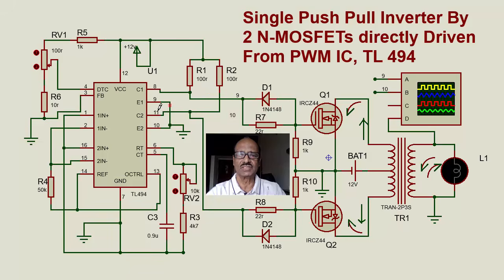So first it goes high and then it goes to ground. So this discharge takes place through this diode. Similarly it happens with this. And then the R and C, as you can see, is selected here. C is this one, R is this one, for selecting the frequency. Error amplifiers we are not using, that is why we have just given some connections here as per the requirement.